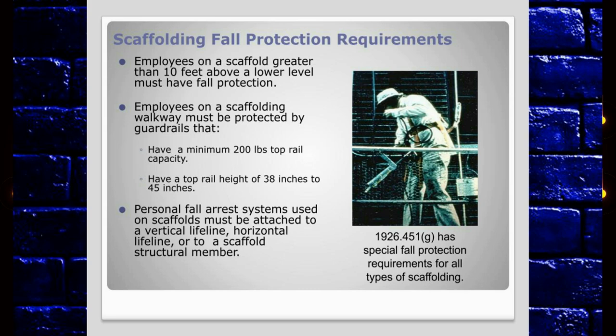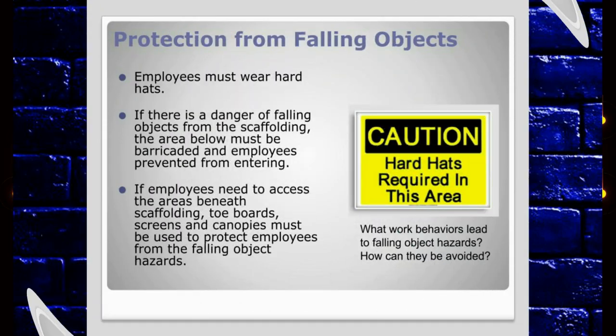1926.451 has special fall protection requirements for all types of scaffolding. Protection from falling objects. Not something you often think about when you're on a scaffold in a high place. Employees must wear hard hats.